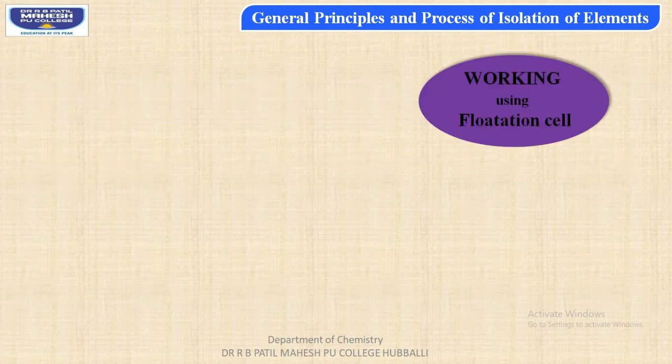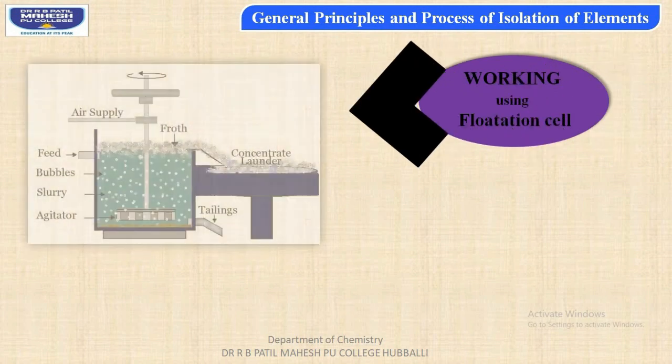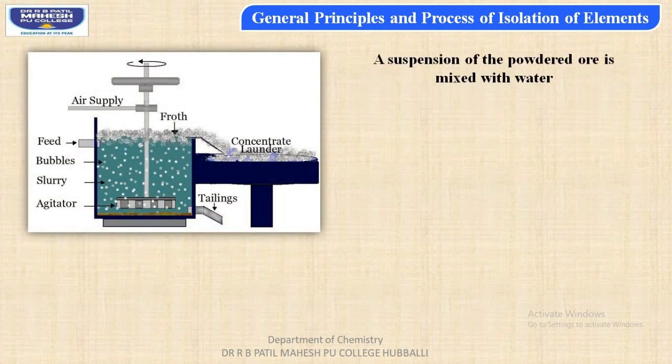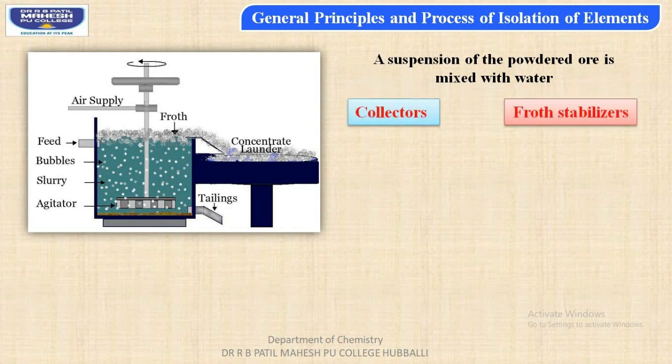Let us discuss about working using flotation cell. In this, students, a suspension of the finely powdered sulfide ore is mixed with water in the first step, and later we are adding collectors and froth stabilizer. Already both the definitions have been given to you.